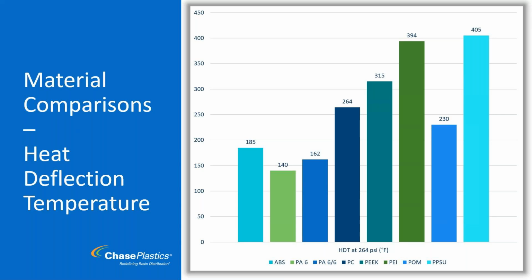Also to note, again, I mentioned engineering and specialty products. If you were to put in commodity materials into here, it would give you a bunch of different values to look at as well. You'd end up with lower temperatures, probably some good impacts depending on which type of propylene you use. Maybe use a no-break copolymer. That'll have a really high impact versus using like a homopolymer, low impact.